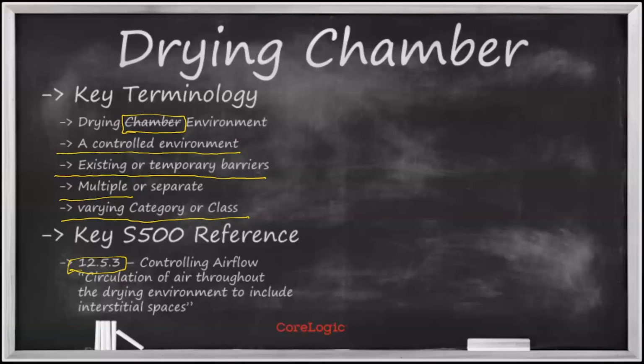Typically when we take these meters that don't have pins, they just have little pads on the back, and we place that along a surface, those instruments have a very limited depth that they can measure with any amount of accuracy. And typically, I treat that limitation at about a half an inch. And I don't really trust anything that a non-invasive instrument gives me beyond a half an inch without a lot more concerted information and thinking about what the instrument is actually telling me.